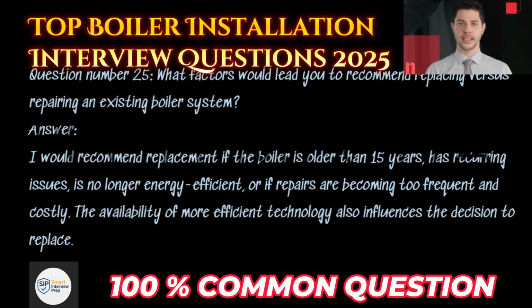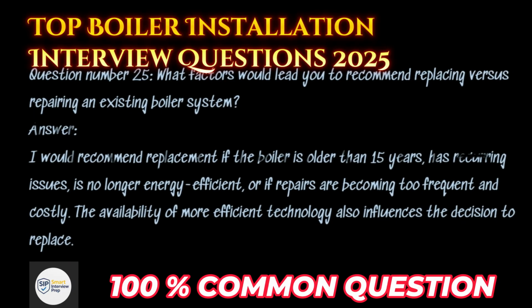Question number 25. What factors would lead you to recommend replacing versus repairing an existing boiler system? Answer. I would recommend replacement if the boiler is older than 15 years, has recurring issues, is no longer energy efficient, or if repairs are becoming too frequent and costly. The availability of more efficient technology also influences the decision to replace.